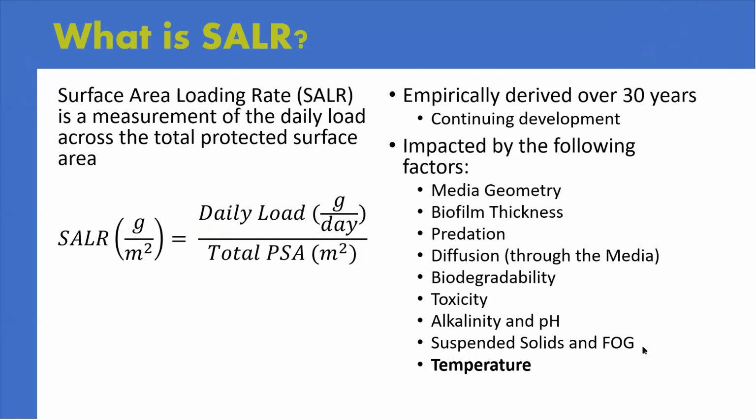So unfortunately, there's no cut and dry answer to what your loading rate is going to be. It's actually an empirically derived variable that has been researched over the last 30 years, and we're still continuing research on. The factors that impact the loading rate that your system can handle include media geometry, biofilm thickness, predation in your system, the diffusion through the media, any biodegradability of your constituents, toxicity that may be present, alkalinity or pH imbalances in your system, suspended solids, fats, oils, and greases that could be in your water, and primarily temperature.